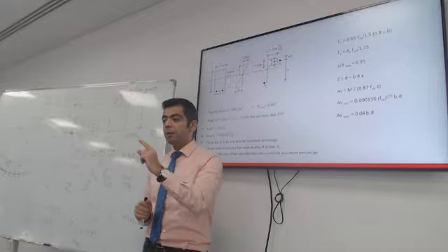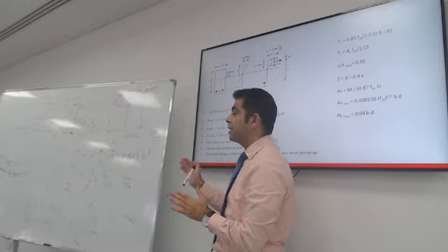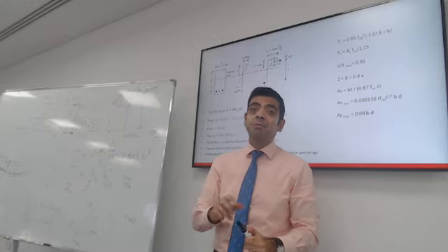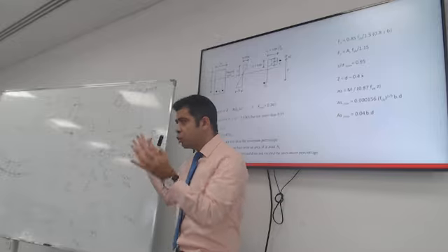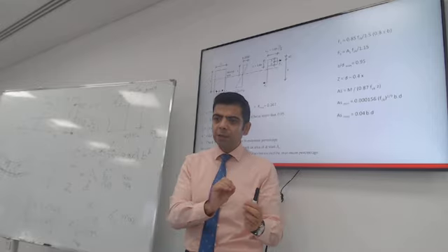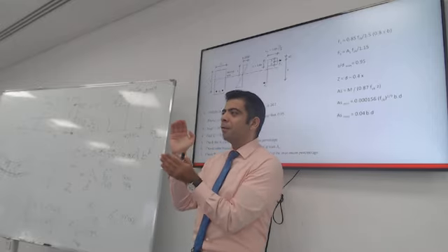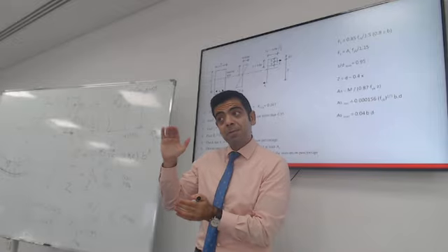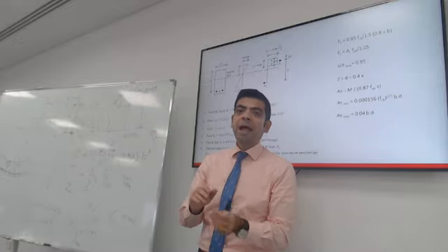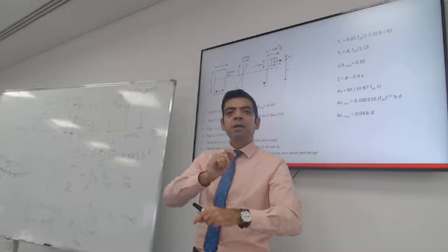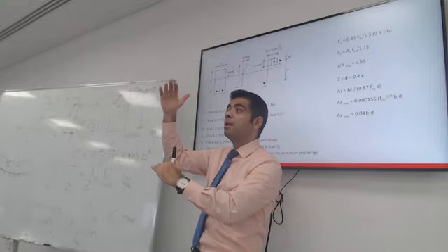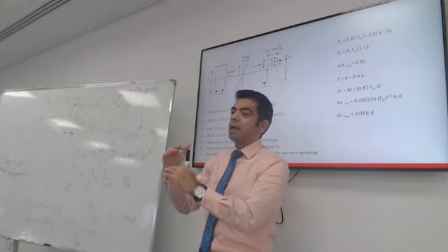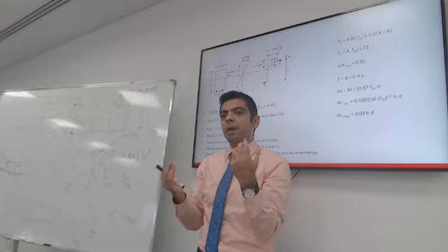The last check is that you don't exceed a maximum reinforcement. Why is there such a thing as too much steel as well as too little steel? You need to be in the perfect zone: less than maximum steel, more than minimum steel. I need you to do these two checks. Calculate the minimum steel and stay above it, calculate the maximum steel and make sure you're less than it. Why is there a maximum area of steel?